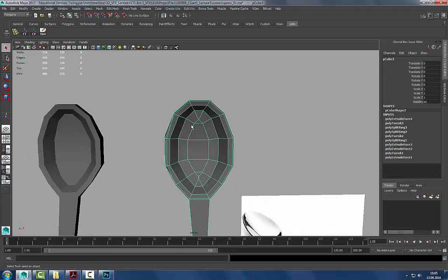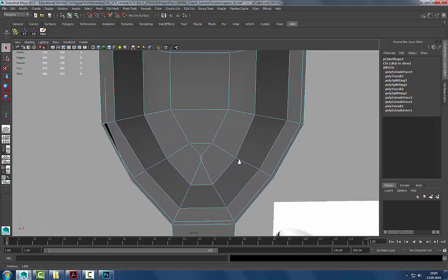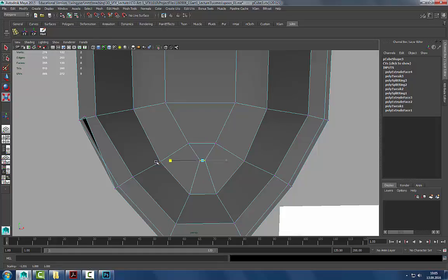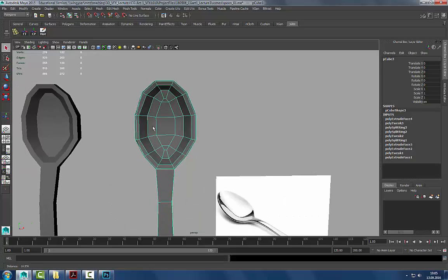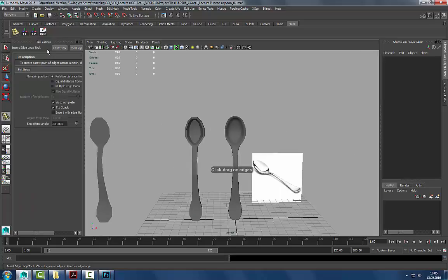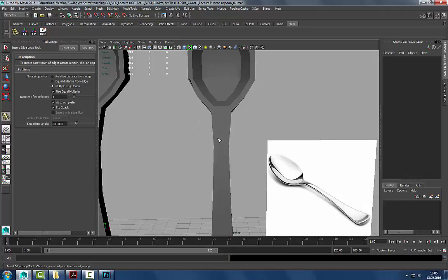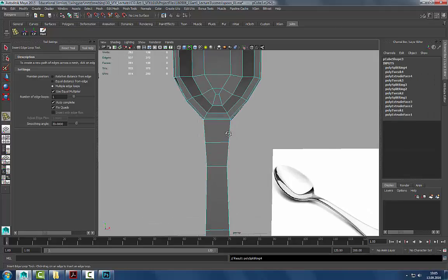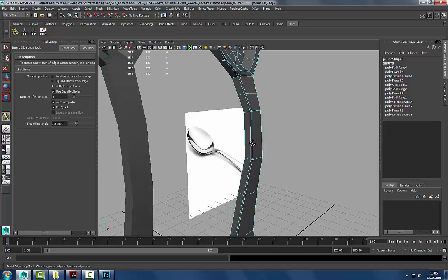Yeah. Yep. Center of the grid, or yep. So that's a funky solution in there, kind of not happy with. Okay. Yes, you go to the edge loop tool. You can double click the icon and then go to multiple edge loops and then press 1. If you have 1, it's going to put it in the mathematical center of whichever path you're doing. So it just finds each polygon it encounters and places it in the middle.